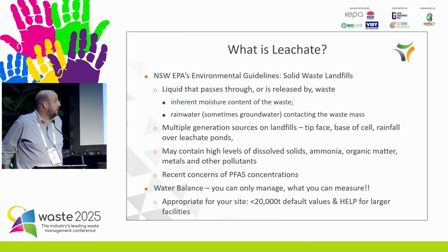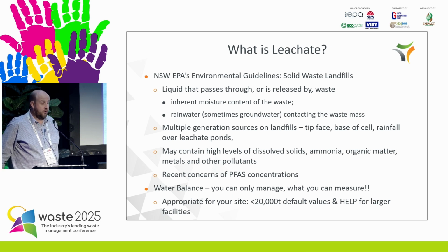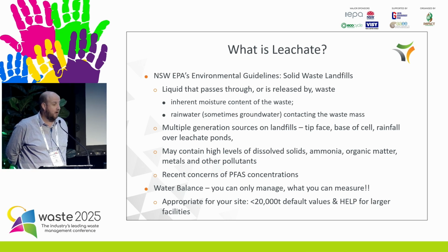Basically, it's water that gets in contact with waste, or where waste has been held. Of course, waste is wet and we try to dry it out, so we're not paying gate fees on water as much as we can. But also rainwater, and some people might have very special sites that have soggy bottoms, as we like to call them. And groundwater is touching the waste, and therefore generating more. There are multiple sources or locations of generation across the site. Obviously, a key one that people also have to be mindful of is your ponds as well. When rainwater falls on top of them, you're going to be generating more and more leachate. And of course, it's got various contaminants of concern, PFAS being the one really high on the agenda of late.